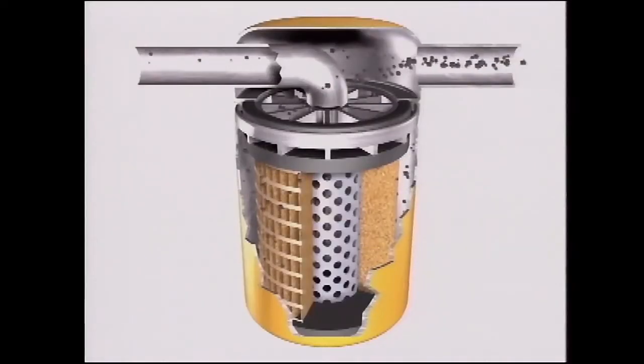All the particles then move onto the filter. Do not assume the filter removes all contaminants in a single pass. As the oil moves through the filter media, many of the particles are trapped, but a few, some large and some small, travel through the media and return to the system through the center tube. Even high-efficiency filters do not remove all contaminants.